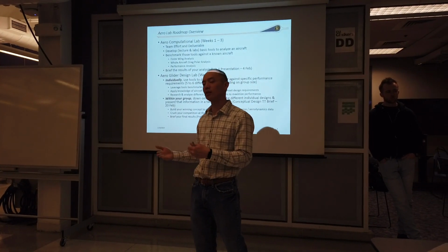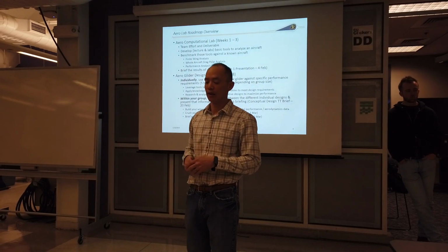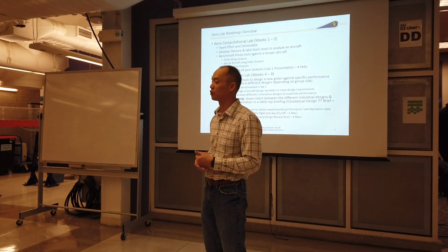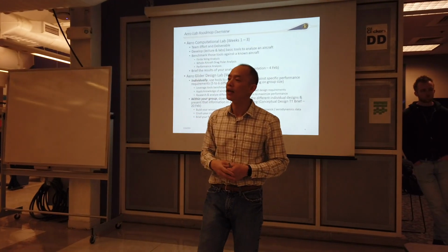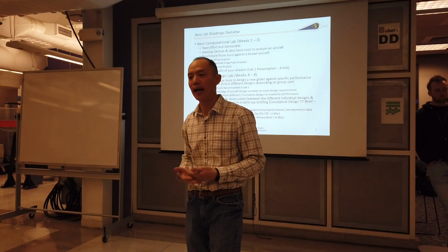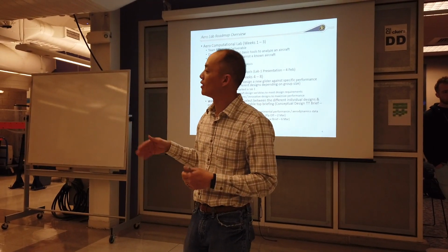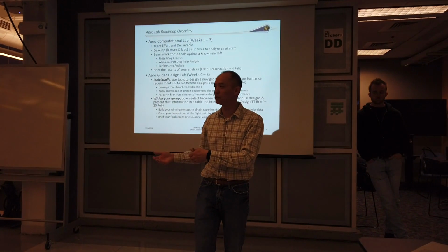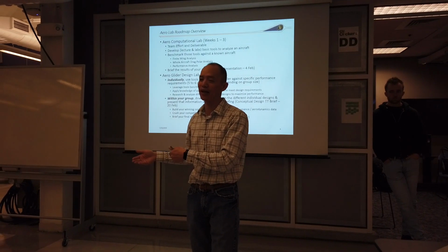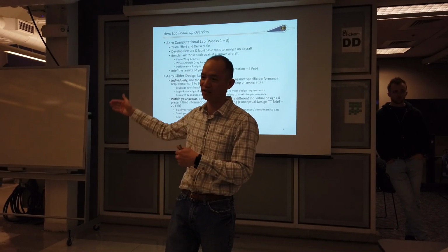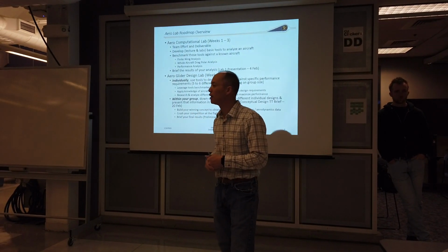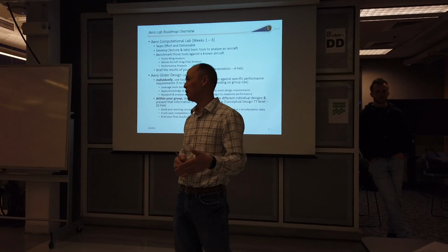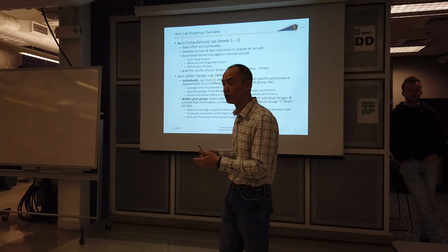You see this a lot, because a lot of design tools are built off empirical data, things that come from industry and actual testing of real airplanes. What they're doing is curve fits to data for like aircraft. So if you use an aircraft that is hugely dissimilar, say you've got a design tool that was built off of data based on supersonic jets from 1980 on, and you're trying to build a glider with it, it may not give you the answer you want, because there are different assumptions that roll into it.